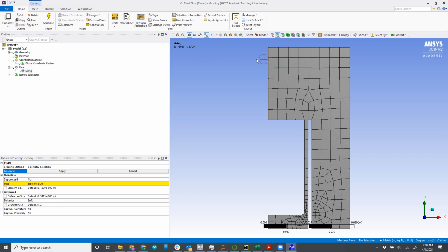Okay, so now we're able to do an edge selection. And we select 4 edges for the sizing. So we'll click here, here, and then the little radius again, and here. So for the element size, we'll do, oops, I did not apply this geometry.